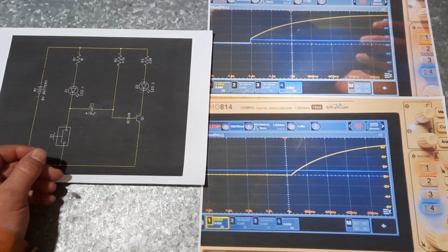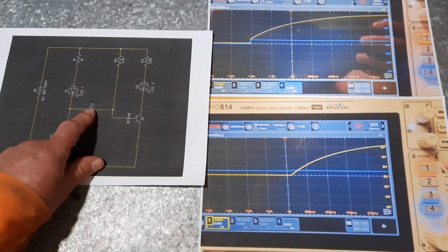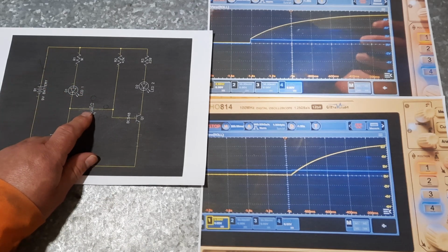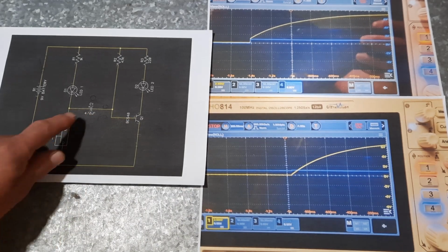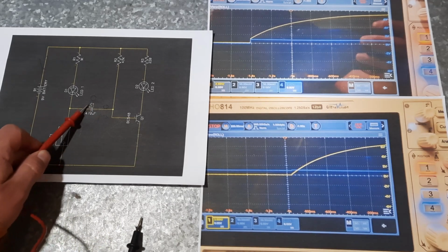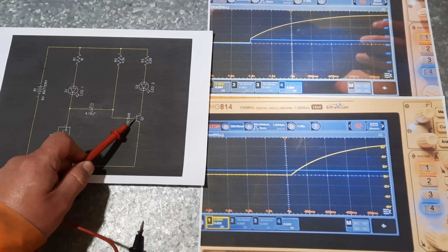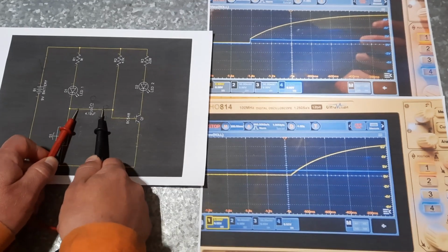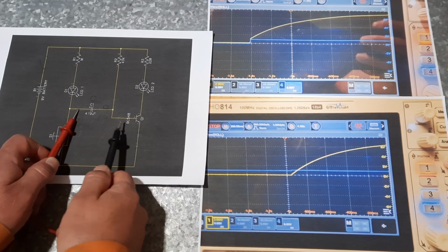As we remember, if we measure from here to here with my finger on this button, holding this button in, this cap has fallen through 0. So essentially we've lowered the floor of that cap, and we've lowered it by this volt drop. While this is connected to the most negative point, this capacitor has taken on a reverse charge of exactly this volt drop. So if we measure from here to here, there is a negative 0.7, 0.8, whatever the turn on voltage of this is.